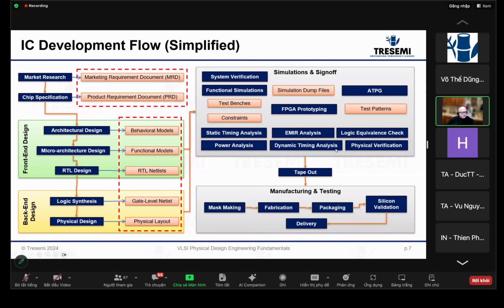And then on the performance side, also power analysis: does a chip consume within the power limit? And there are behaviors in the timing area that cannot be caught by static analysis, even though static is really the math, the complete timing verification, but it cannot simulate interaction between different timing paths.